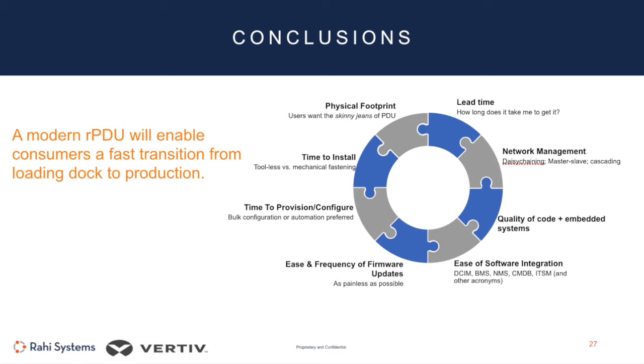If you wanted to use the fault-tolerant daisy chaining via spanning tree protocol, the number of PDUs there would be 40. And you can also have some combination between those two. A lot of customers like the approach where they have a 2 PDU arrangement within a given cabinet.